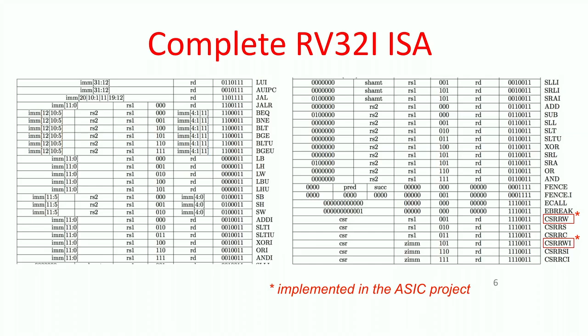The other parts of these diagrams show the encoding. It shows how the instructions are encoded in a 32-bit word. We'll talk more about this next time, but we'll take a 32-bit word, which is the representation of an instruction as it is in the memory of the machine or in the instruction cache. And we assign a different interpretation to each field within the instruction depending on the instruction type. Some of the fields specify where the operands are in the register file, or give us information that we can use to compute the address of the operand that's in the memory in the case of the load and store instructions.